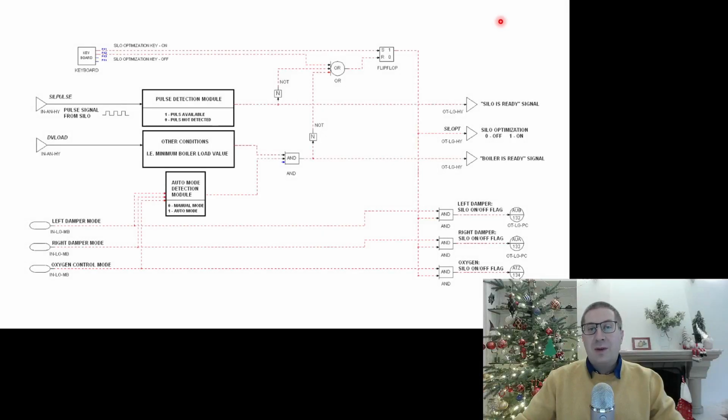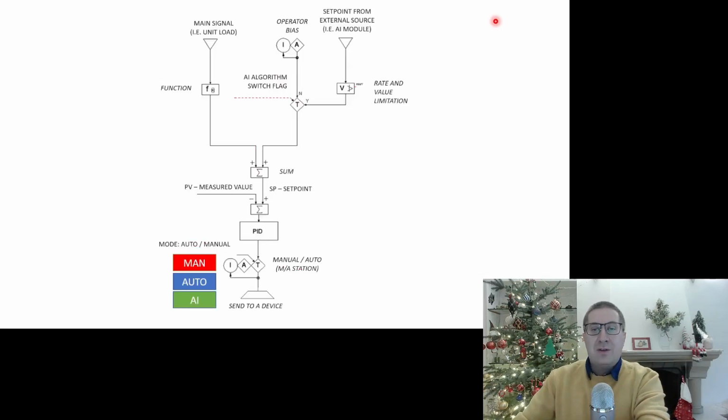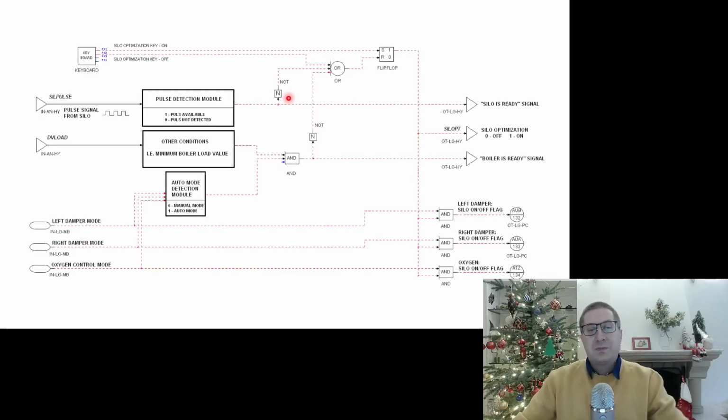If you would like to implement the AI method that controls devices, we should also implement the logic within the control system that decides about the value of this particular flag, right? So we also have to change the operator graphic and, let's say, add the button that represents the state of the AI algorithm.